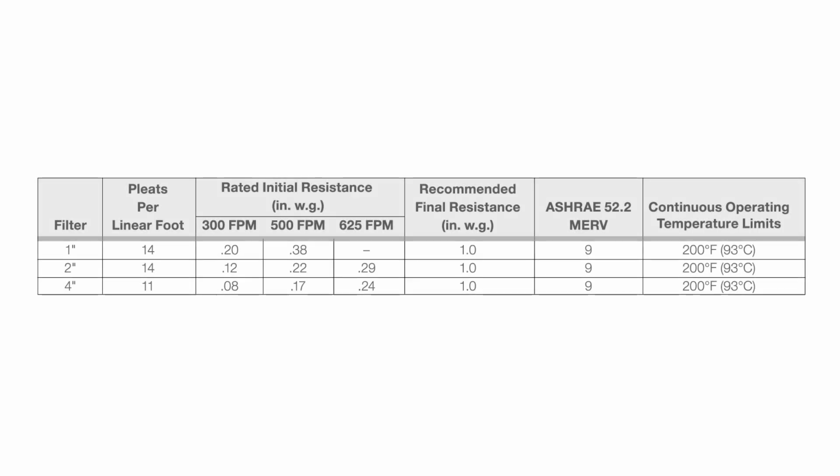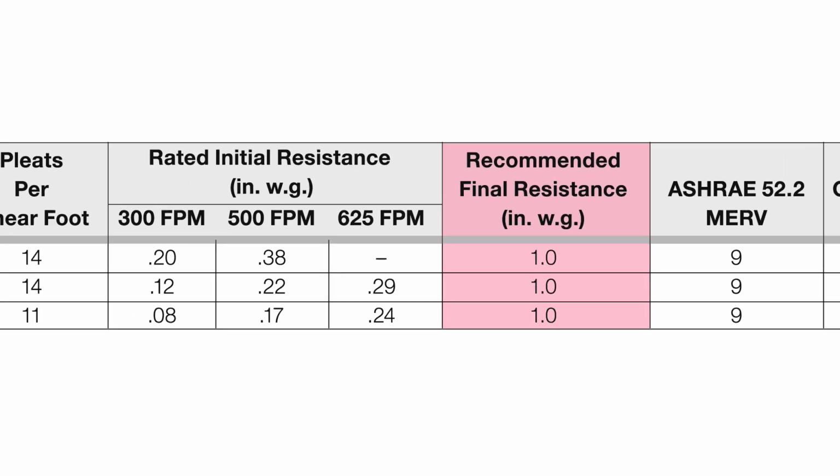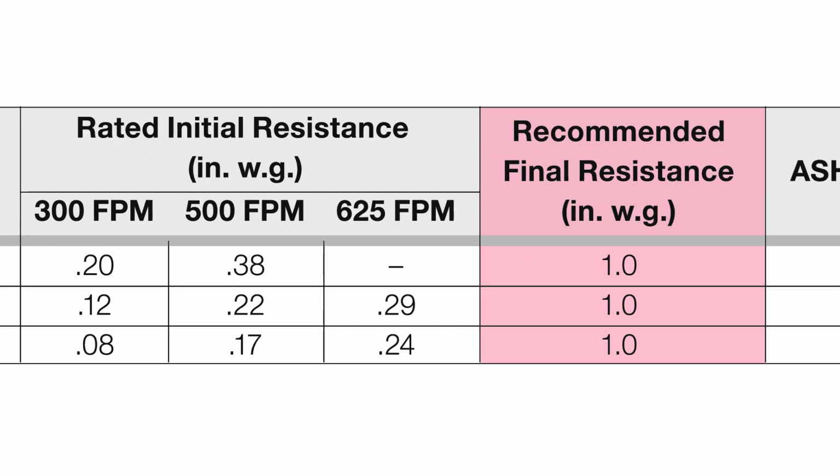The manufacturer will list the maximum rated pressure of each filter. You can see that here on the specification sheet. This is the calculated pressure that the manufacturer has determined the filter can safely hold before affecting its performance. When it reaches this amount, the filter should be changed.